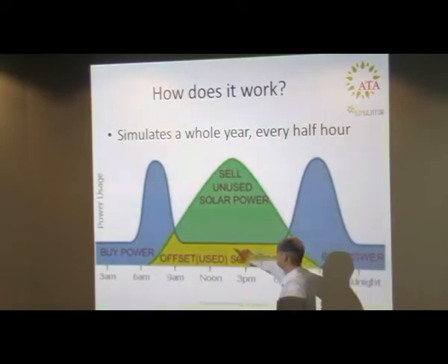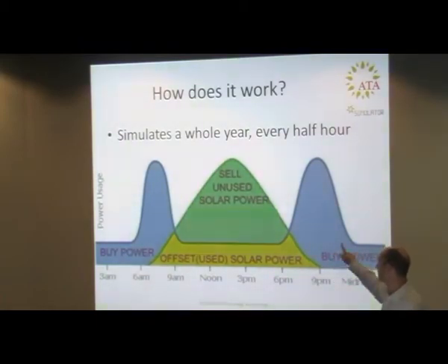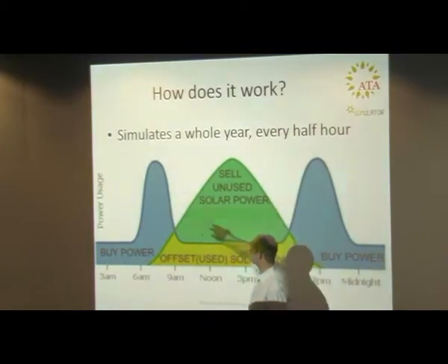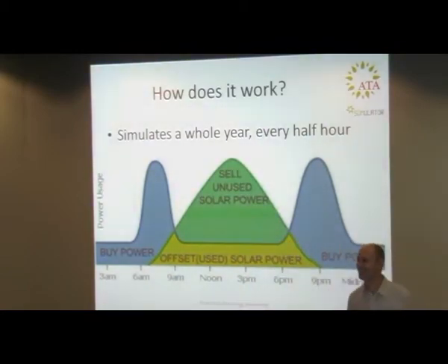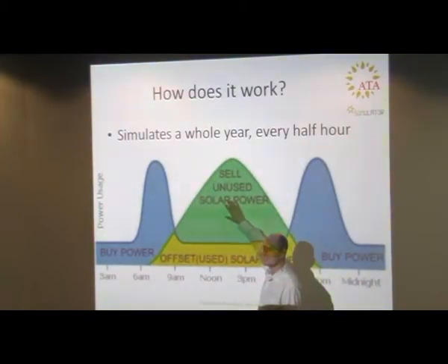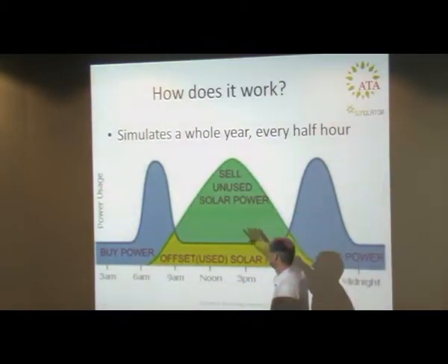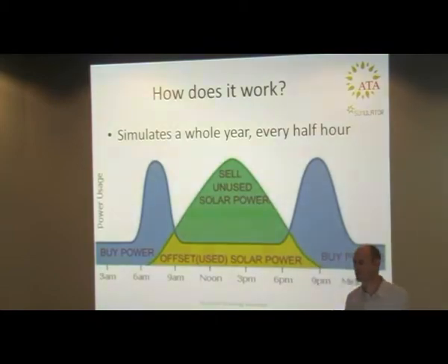If you've got good eyes, you probably notice this strange green rectangle here. This was a slide that we've had for a few years now, and that used to say a premium feed-in tariff rate. Previously you wanted to have all this export in the middle of the day, and that was great. And it's still great if you're on one of those contracts from a few years ago. But if you're installing solar now, that's not what you want. You don't want to be exporting all this during the middle of the day because you're not earning much money from it.